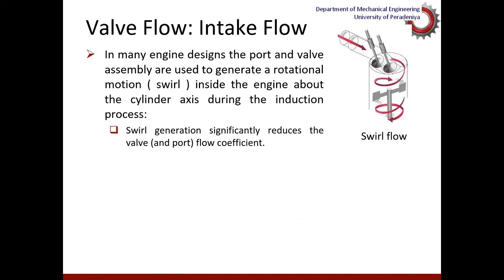In addition to these flow patterns, it is very much required in internal combustion engines to generate certain special types of flow patterns in the intake system. One such type is the swirl. Swirl means the rotation of incoming air, which enables generating turbulence and mixing air and fuel together, for example in the case of spark ignition engines. Accordingly, this intake port is geometrically modified in such a way that the swirl flow is enabled.